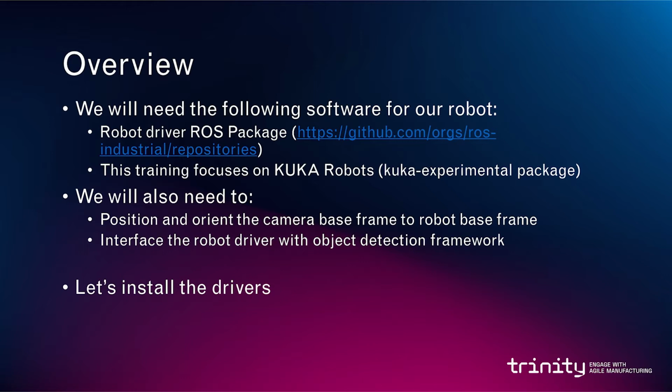We will need the following software for our robot, which is the robot driver ROS package, and this package will be focusing on KUKA robots with the KUKA experimental package, which is the package we will be installing. We will also need to position and orient the camera base frame to robot base frame and interface the robot driver with object detection framework.